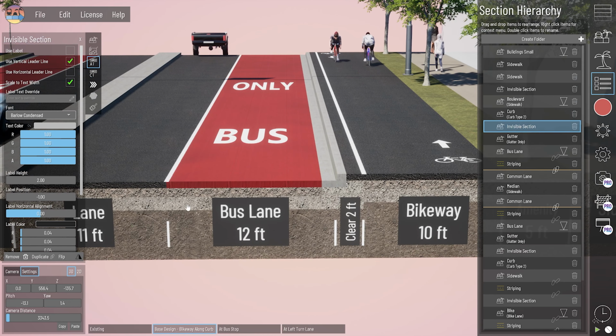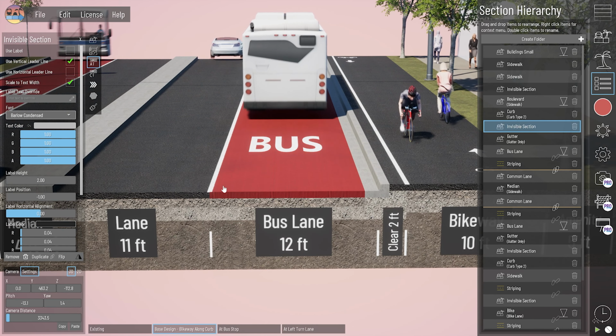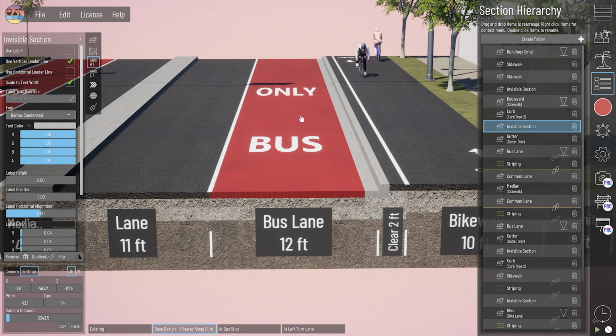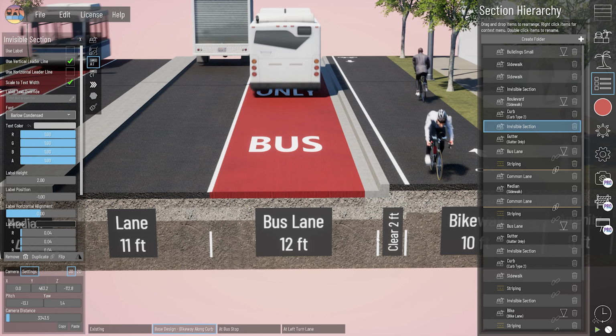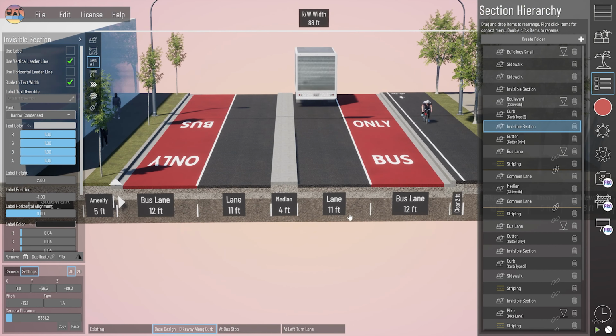It's a really nice way when you're trying to fine tune your section labels. Maybe there's a certain combination of sections where you want to see those all measured differently. You have those label overrides and invisible sections to put in stems and custom labels using those auto labels as well.